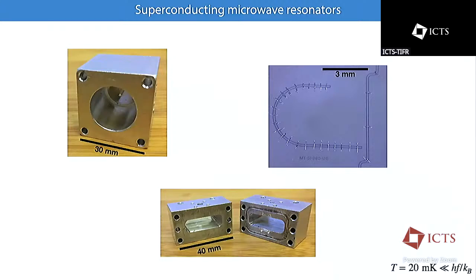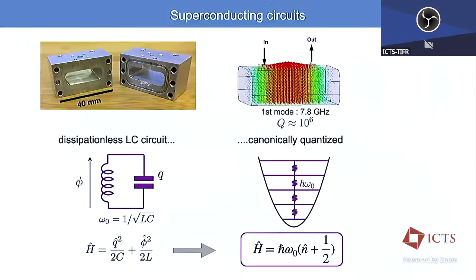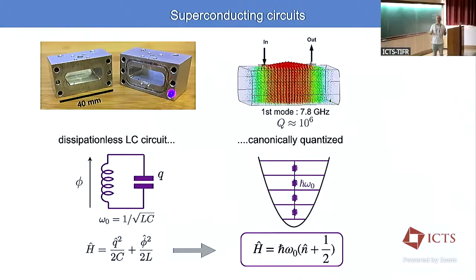And these modes will be really high Q. By really high Q, I mean that you simply take a piece of aluminum, you drill a hole like this, and you close the 2 parts, and you get a quality factor of 1,000,000 without much more work. So this is really impressive. We can get even larger quality factors with more advanced structures.